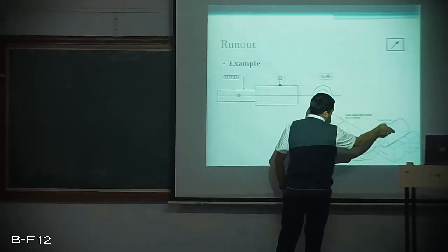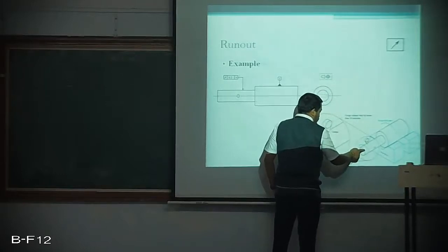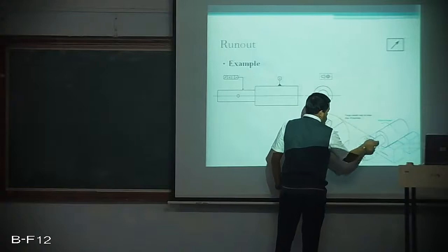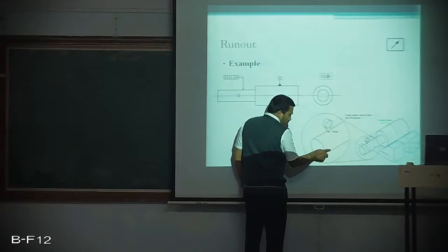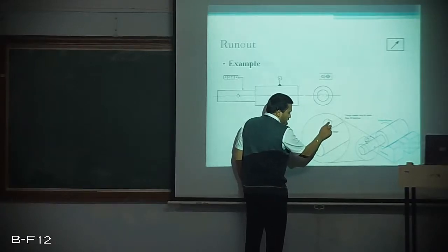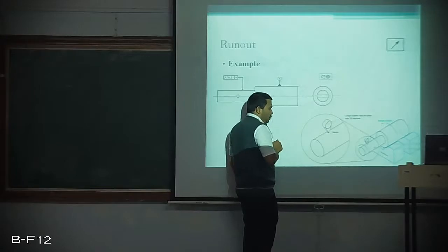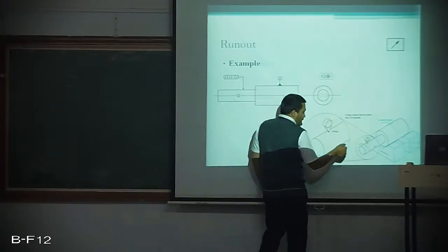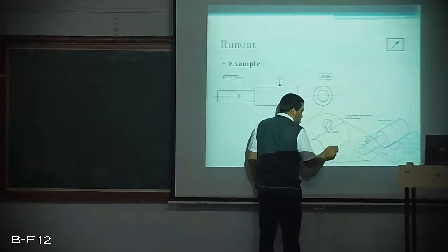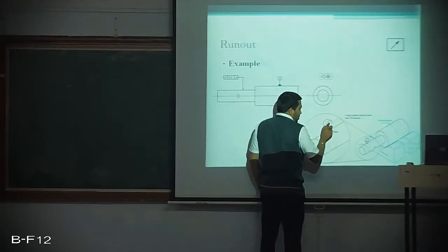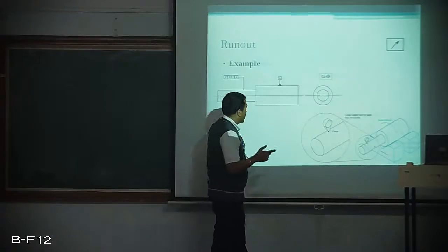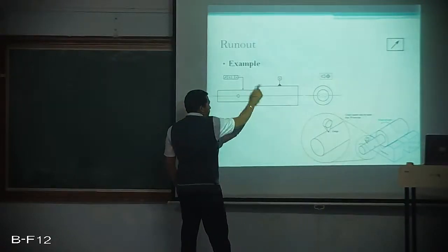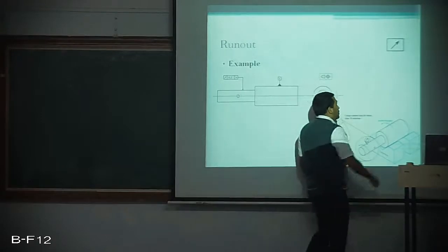So this is the first shaft, it is rotated by 360 degrees, and this second shaft has to be manufactured with the runout with respect to this. If you place the gauge and rotate by 360 degrees, these will be the variations you can see. These variations must be well within 0.030. Earlier when it has touched, there is no variation. When it has moved through 360 degrees, you can see the difference over here, and this difference must be well within 0.030. That is what is indicated in this particular drawing. And the symbol used is this.